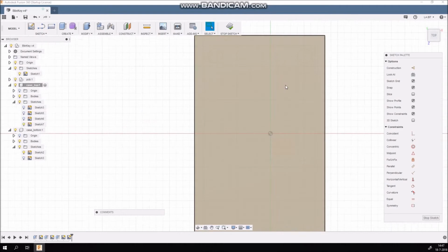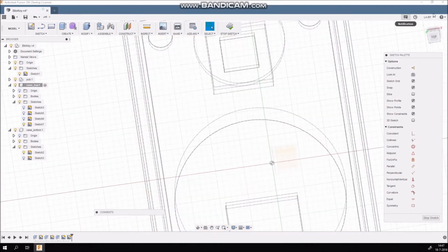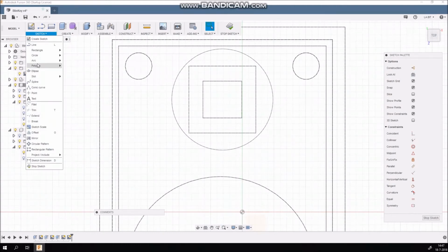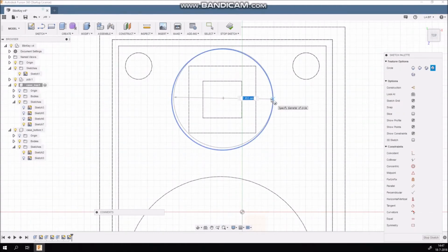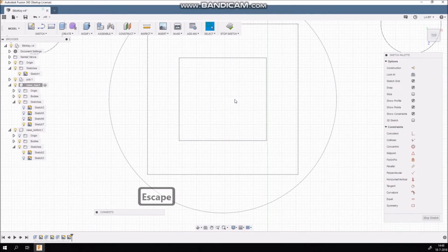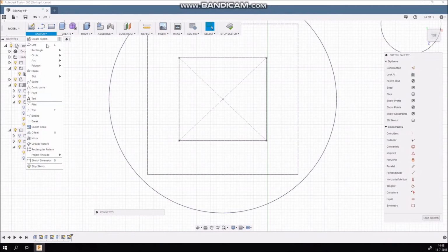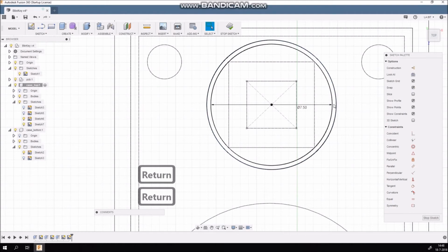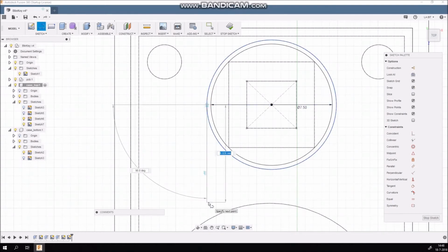And every time you're using a sketch to make something, Fusion will hide the sketch. So activate the sketch again and you can make a new circle on the same spot. Make another circle, which is actually a half millimeter smaller. We're going to make a slit in the top, so you can press it actually, and it works as a button. Therefore make 2 slits going down.